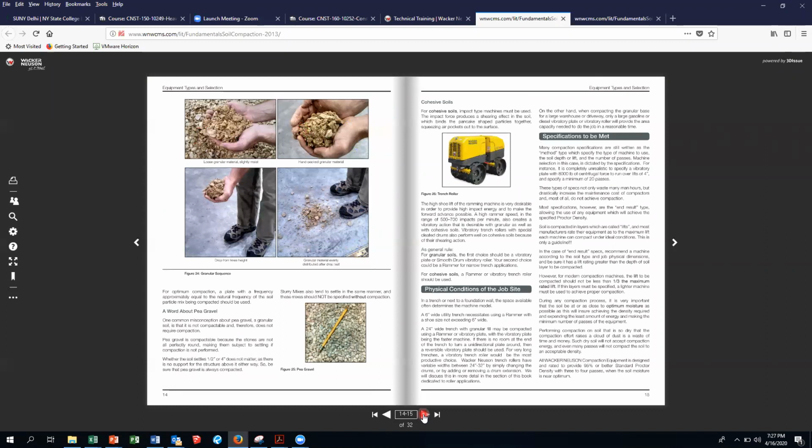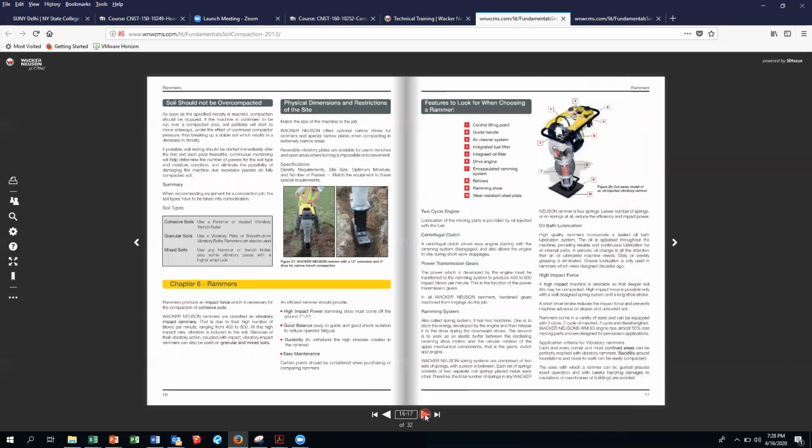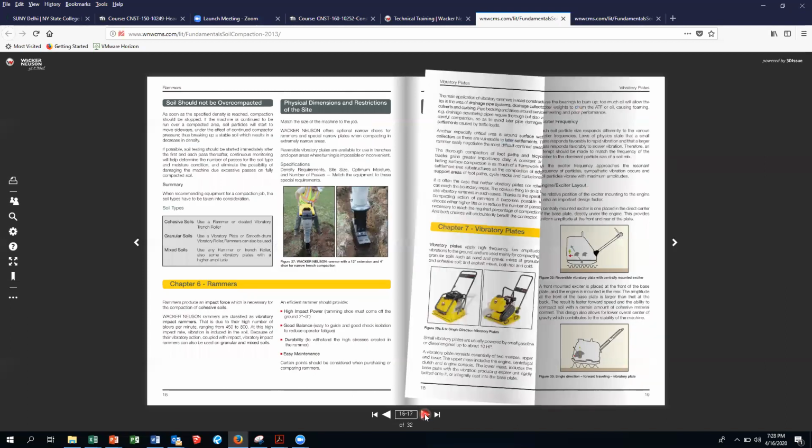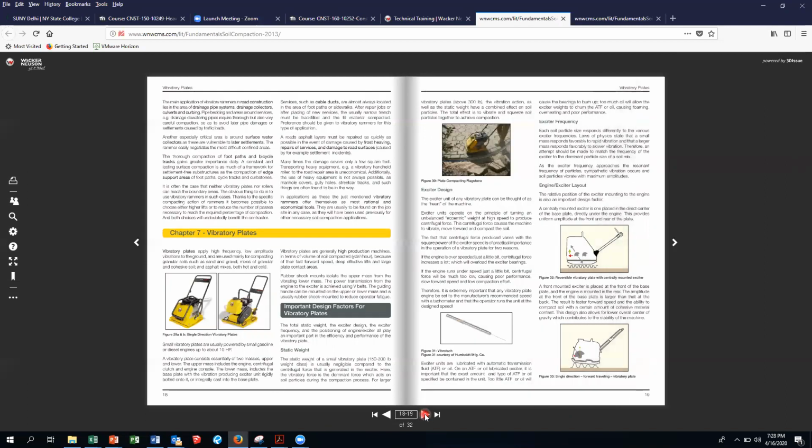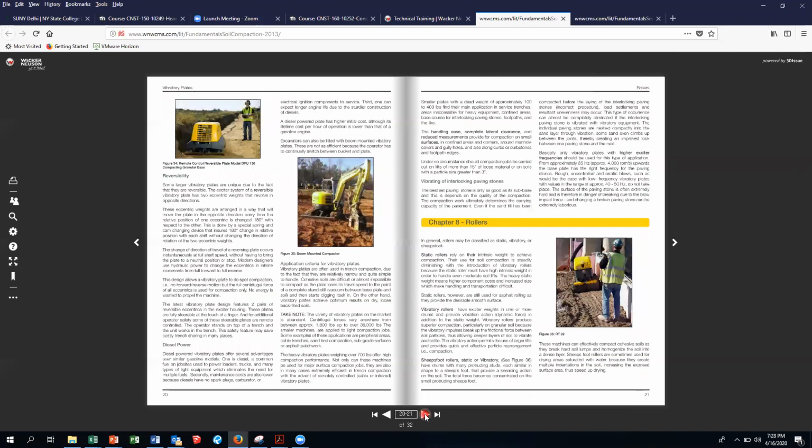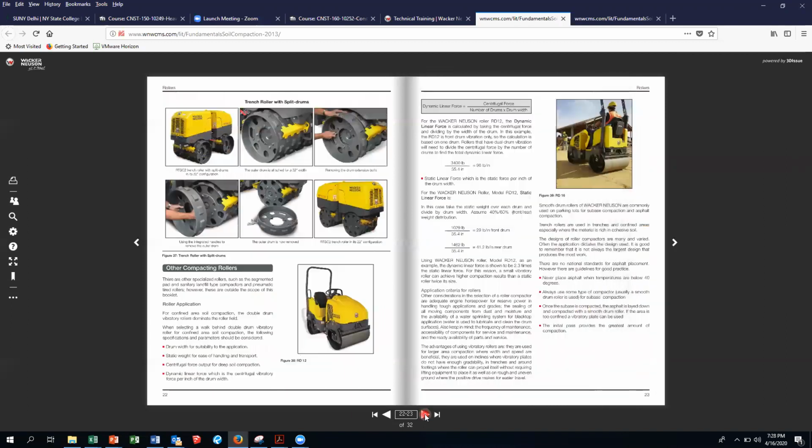Because if all of a sudden they're asking about compaction and you say to them, well, where's your Proctor curves? I'll tell you what, that's where the cheese starts to bind. Their ears will perk up. This is all about good compaction so you don't get differential settlement. Okay, vibratory plates, rollers, right? Sheep's foot rollers.